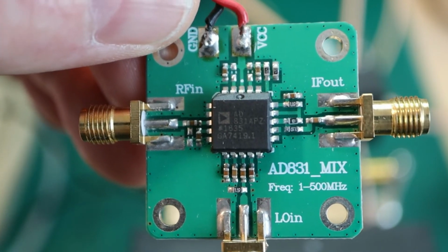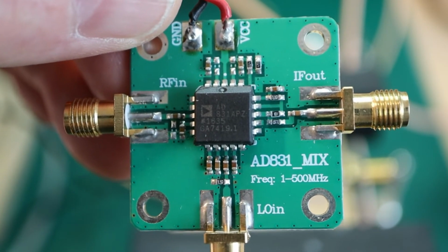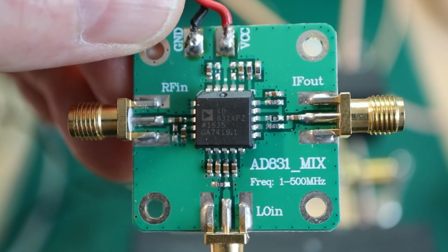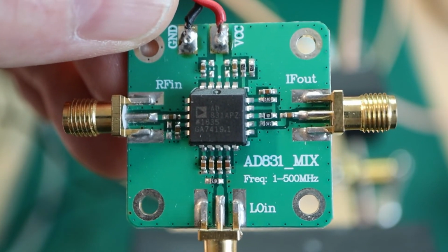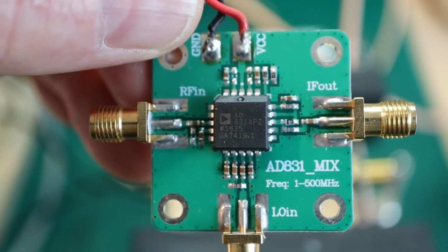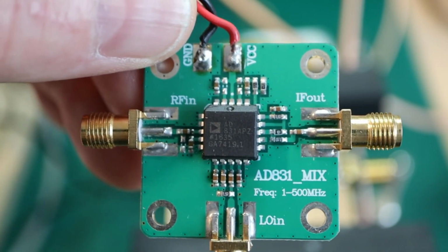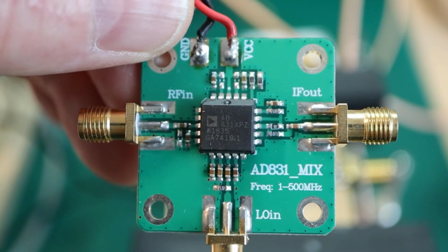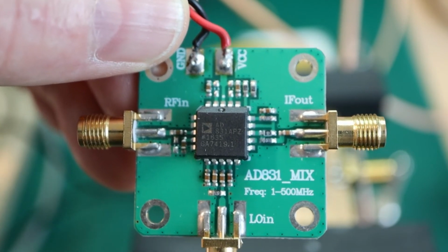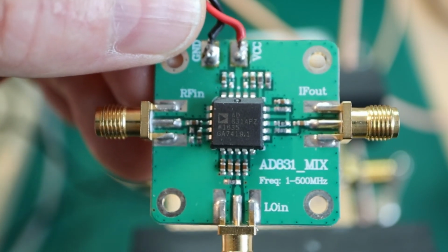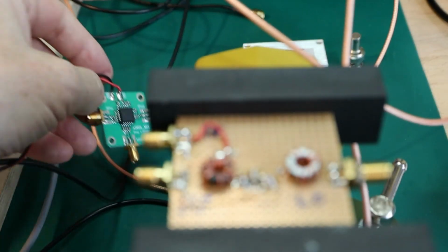One for the intermediate frequency of 9 megahertz. The other one I use as a product detector. And the third one is used to convert this 9 megahertz intermediate frequency to 300 kilohertz for the input to my analog digital converter, and then make a spectrum analysis on top of it with a fast Fourier transformation. So let's start with this analog SBL1 mixer. Let me see.